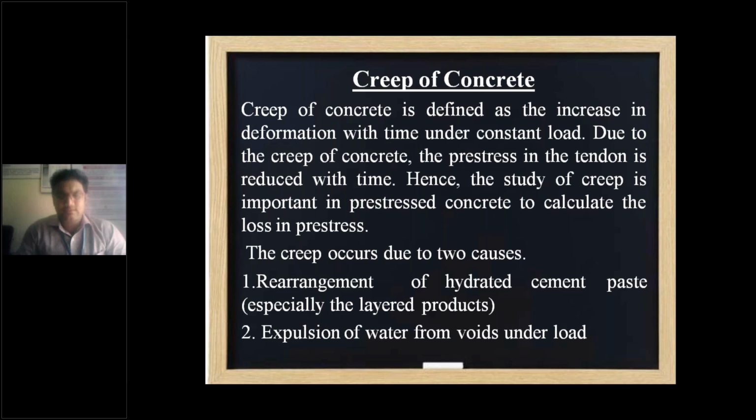So due to the creep of concrete, what happens? Prestress in the tendon, or whatever wire we are using for prestressing, is going to be reduced with time. Understood? Whenever the concrete has creep, obviously it will reduce the tensile strength in that particular tendon, which also reduces the strength of the concrete member. Okay, so the concrete needs good creep behavior.